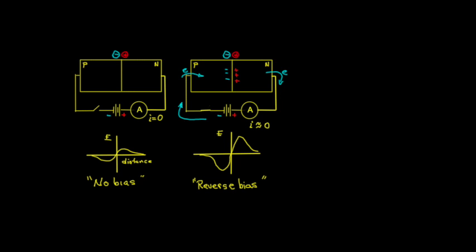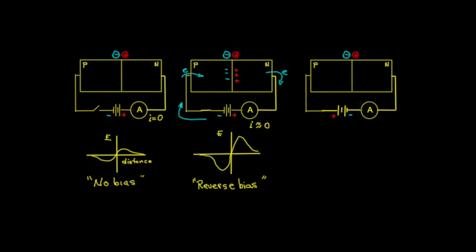If we connect the battery in the opposite direction, electrons are pumped into the n-type side of the junction where they can recombine with the holes that have collected there. A similar process occurs on the p side. Electrons are drawn off toward the positive side of the battery. So the potential barrier is pulled down and the current can move easily from one end of the semiconductor to the other. This is known as the forward bias condition.